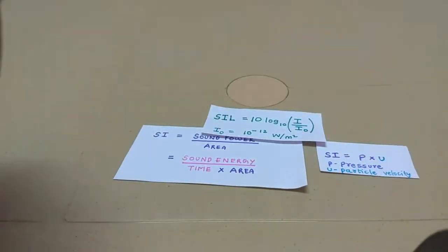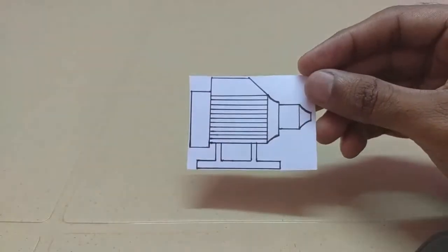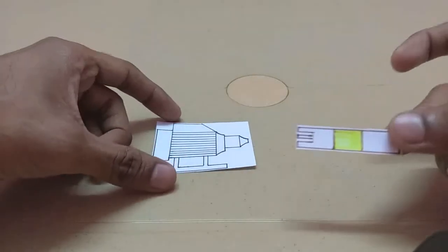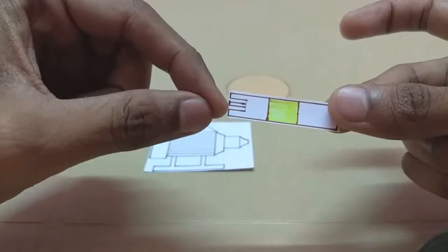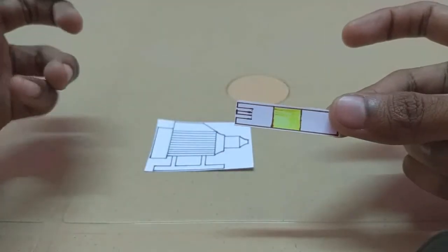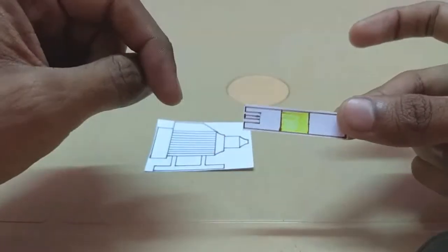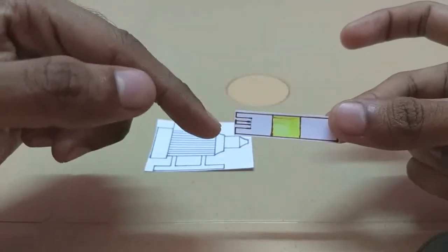Now let's look at the measurement techniques. There are many ways to measure sound intensity, but today I'm going to discuss the method which is predominantly used in industries, which is nothing but scan and paint. So in order to measure sound intensity, first we need to choose a machine or a noise source. In this case, I'm choosing a pump. Let me walk you through the instruments required. First, we need a PU probe, which is nothing but a pressure velocity probe. This probe has two closely spaced microphones right here. The purpose is first to measure the pressure as is and to measure the pressure gradient between these two microphones. Now the pressure gradient, whatever is measured, is actually proportional to particle velocity. So you're going to get the information of particle velocity just by measuring the pressure gradient.